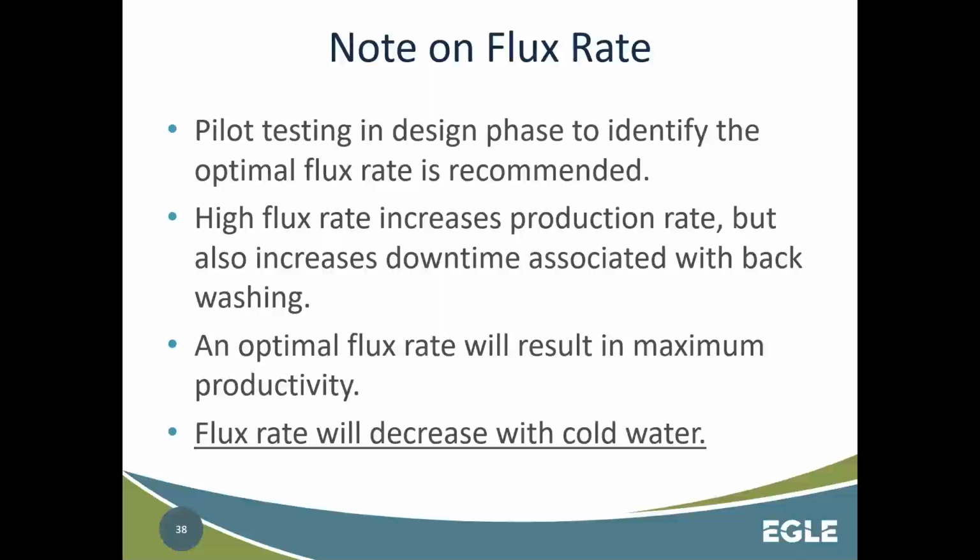And the advantage of a high flux rate is it increases your instantaneous production. But as things plug up on the outside walls of those fibers, it will increase downtime associated with backwashing. And so there is kind of a sweet spot, and that optimal flux rate will result in maximum productivity throughout the production day.